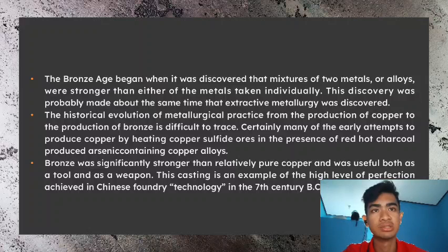Other publications suggest that a soft bronze or gunmetal is formed when 60 parts of copper are mixed with 1 part of tin, and that a hardened gunmetal such as was used for bronze ordnance is formed when the proportion of tin is approximately double. The hardened gunmetal contains 88% of Cu.